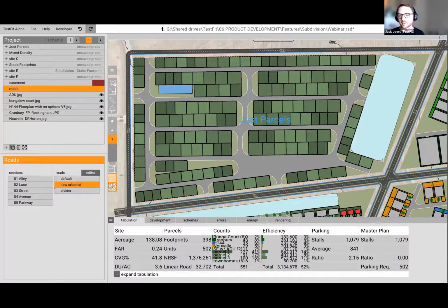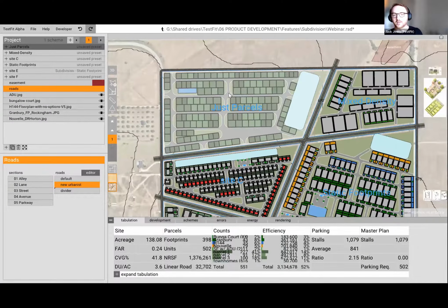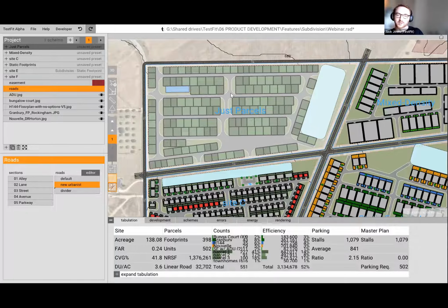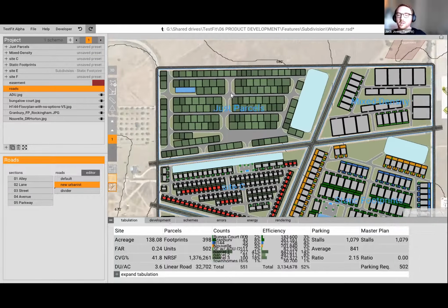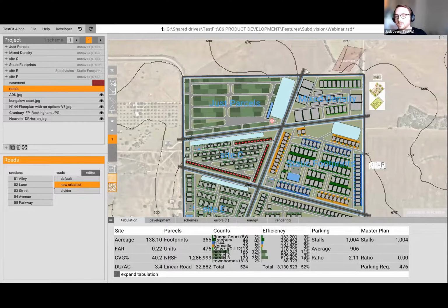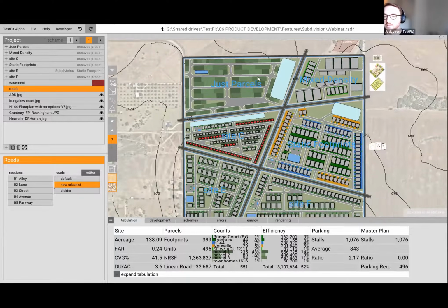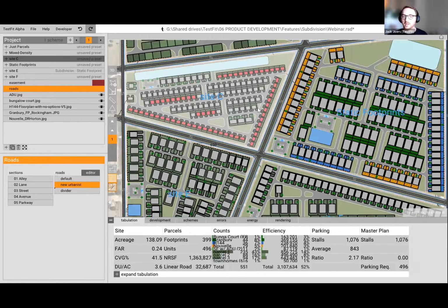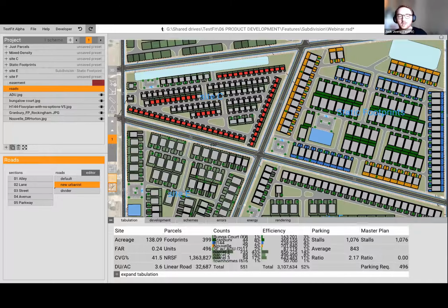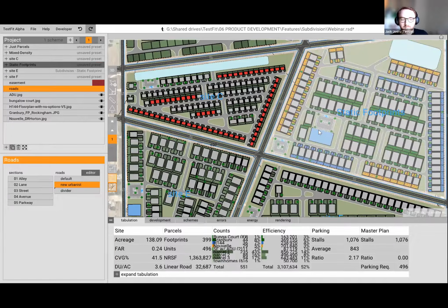Yeah, absolutely. There's a question about other lanes, other types of uses for roads, like collectors versus arterials and that sort of thing. What Nat was just showing is our road network that he's drawn up outside would be your arterials and more editable within that street section. We can also have bus lanes, bike lanes, green buffers, all that sort of thing. Within the sites, they're all local roads that are all controlled together within that drive aisle parameter set that he was just showing, which could include bike lanes and things like that within that width. Awesome.